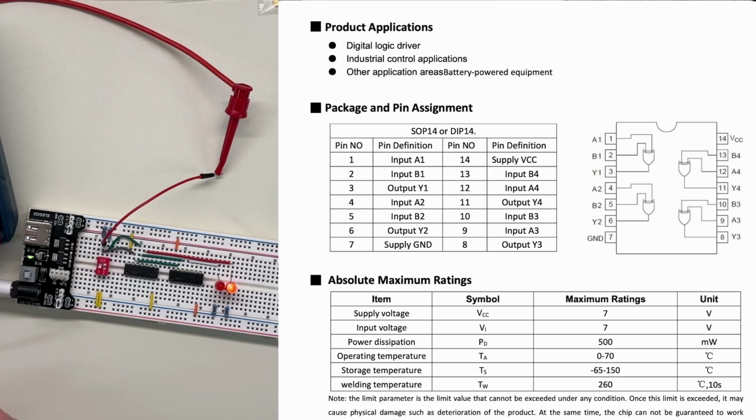What's this about? Absolute maximum rating. So VCC can handle 7 ratings. What does that mean? I guess they mean 7 volts, because the unit is volt. It can handle 7 of them. This seems remarkably obtuse in any case. Input voltage can be 7 volts. I guess that's probably the voltage on one of the pins, like the input. I guess input voltage is different from supply voltage. Operating temperature 0 to 70 Celsius. So I guess you can't boil this, but it can withstand a lot of cold and heat if it's not running, I guess.